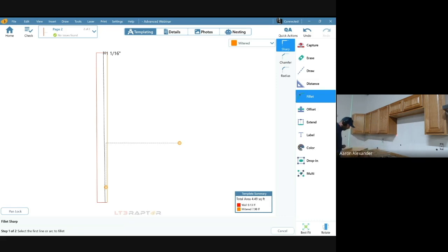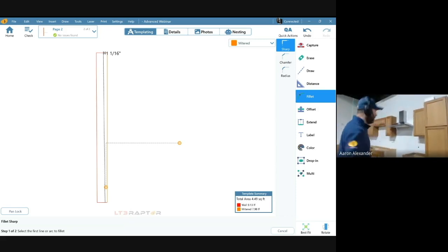Now, when it comes to setting the plane, again, I can't reiterate enough. When we're talking about vertical surfaces, what are we gluing the piece of stone to? We're going to glue it to this wall. So all 3 plane points need to be on that surface, on that wall, right? So when we go to set this plane, it's basically we can go lower left, right on the wall, lower right, right on the wall, upper middle, right on that wall, right? So you'll see the common theme here is all 3 points are on the surface or a representation of that surface in space here, right?